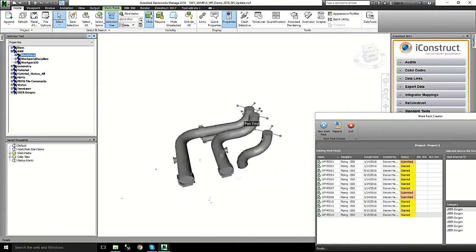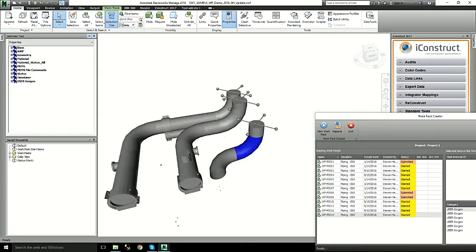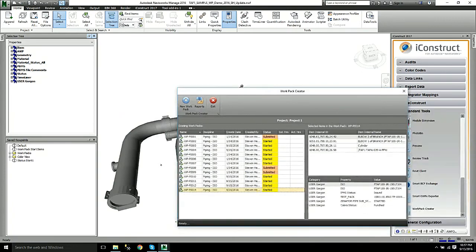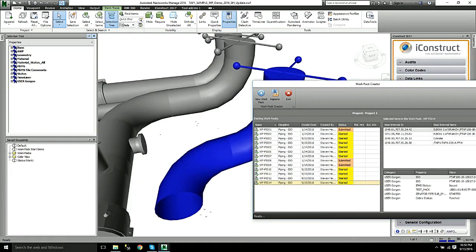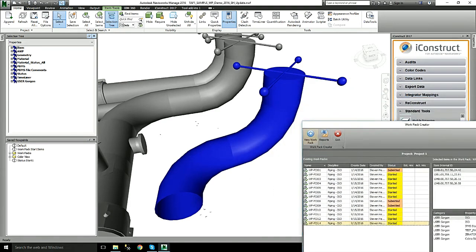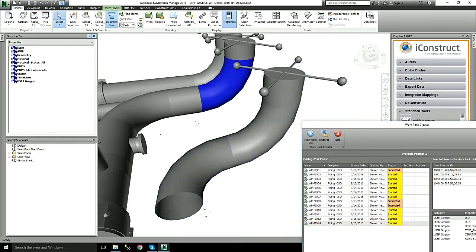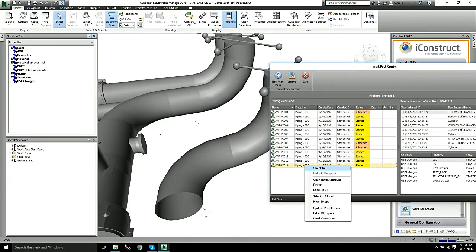We'll move in and zoom close to where we want to be picking, select one item and drag it, holding the left click and dropping it into the window on the right hand side. So you can see that very, very simple move there. Now if we select that in the model, we'll highlight everything here. So we just selected one item in the model, dragged it into the right hand window, dropped it in, and it updated everything at the isometric level.